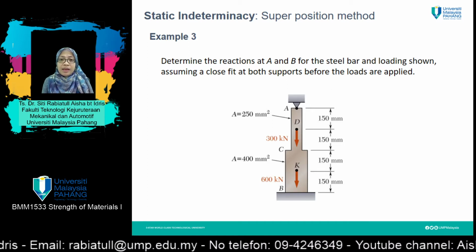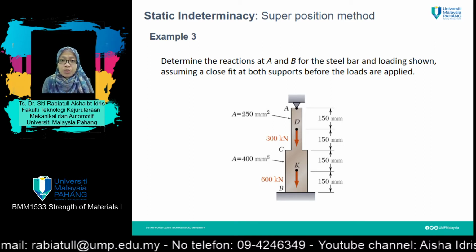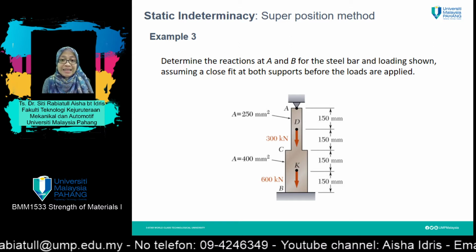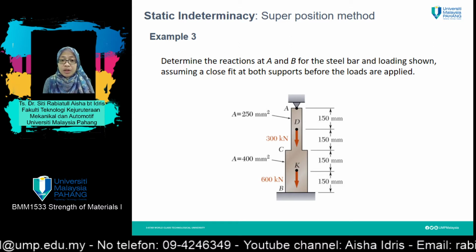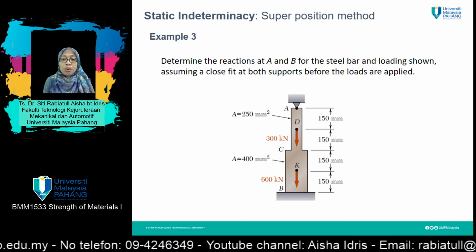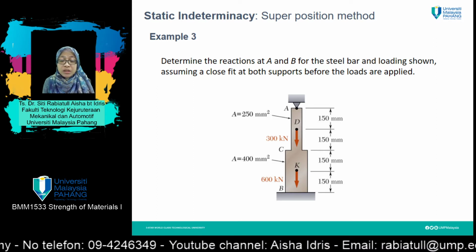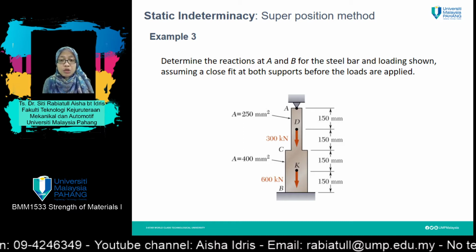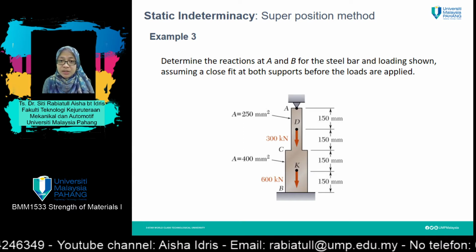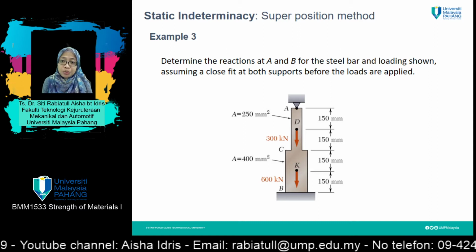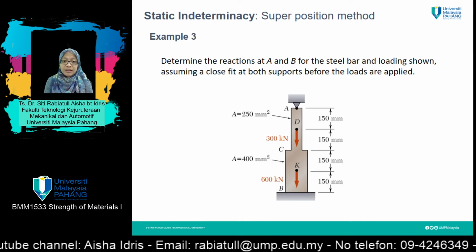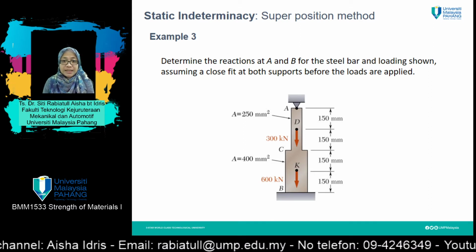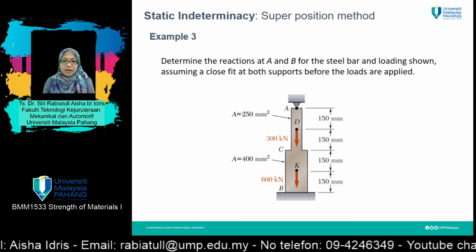But then there's another case, which is known as statically indeterminate. This is because we cannot solve the problem only by using the equations from statics or from the free body diagram, and therefore we need to apply the superposition method. How to apply this superposition method? Now let's look at this example.